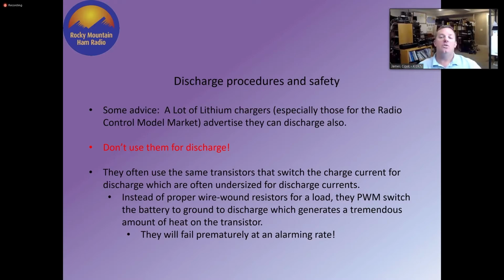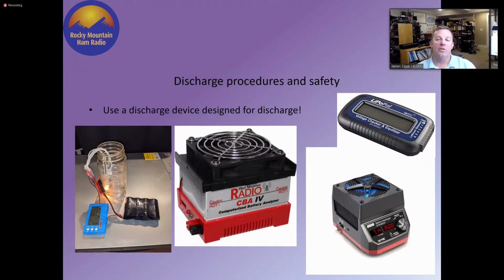And instead of using something like a wire wound resistor or some type of good load, they use pulse width modulation on that transistor to switch the battery directly to ground, which generates a tremendous amount of heat on the transistor, and they fail. I can't tell you how many good quality chargers I've had completely fail when I use them for discharge over and over again. So instead, use something designed for this.